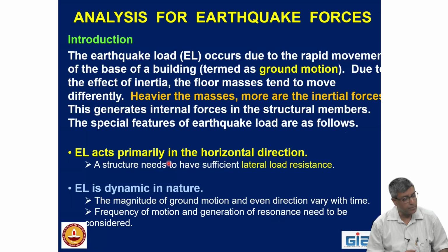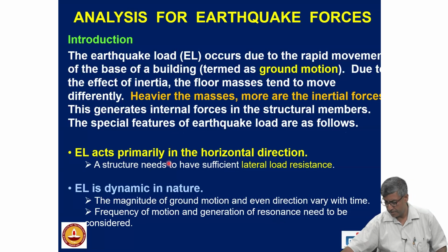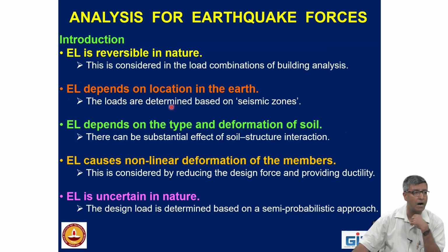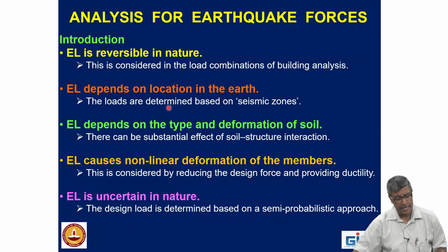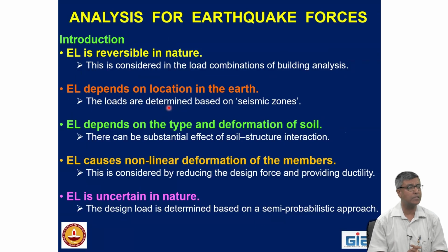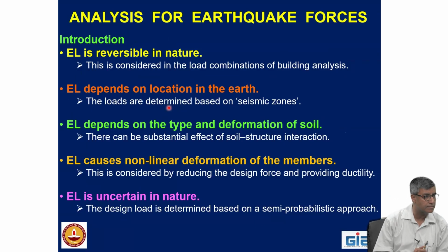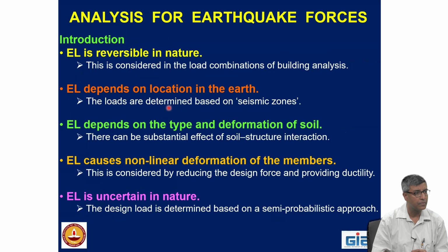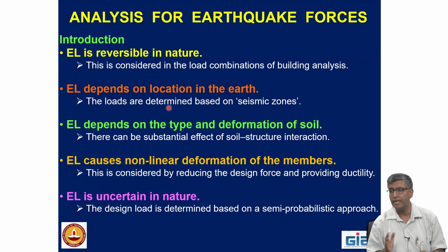Earthquake is also dynamic in nature. It is reversible. This also depends on the location of the earth. That's a whole topic by itself, the earth geotectonics. It depends on the type and deformation of the soil. That means once you are trying to do some seismic hazard analysis, you are trying to get the base rock motion. But then depending upon the soil fill, the earthquake motion can change.